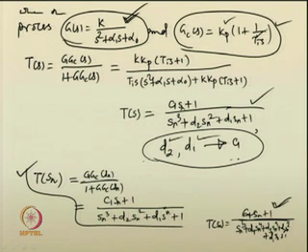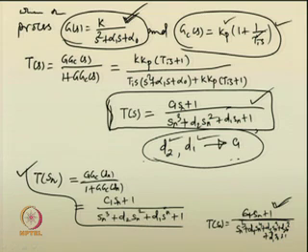So, what have we been doing? We are trying to find some standard transfer functions which are known to us and which are tested also, so that their time response will be highly satisfactory. Then the closed loop transfer function can be used by back calculation to calculate the unknown parameters of a controller, which will definitely yield very satisfactory closed loop performance of a closed loop system.